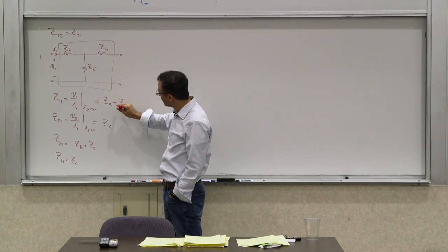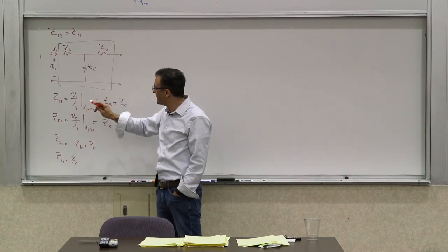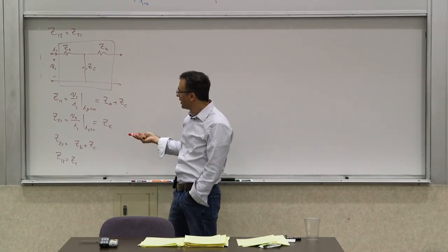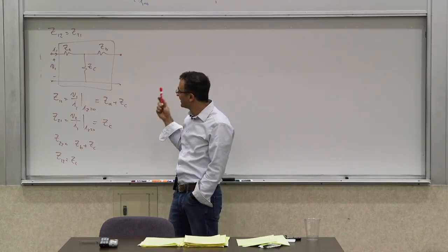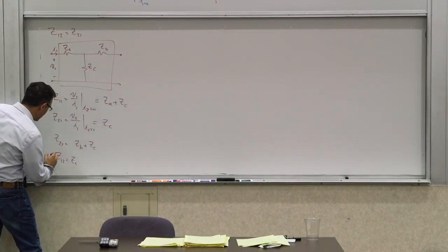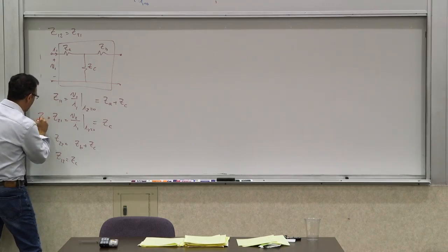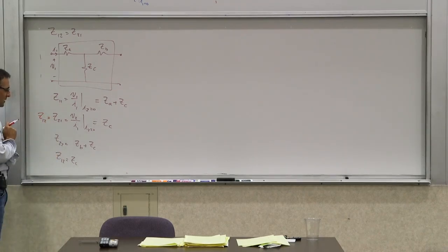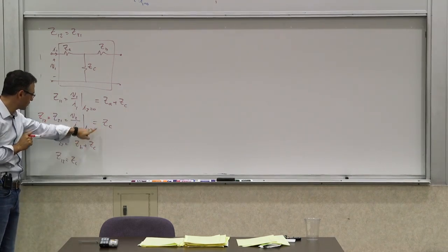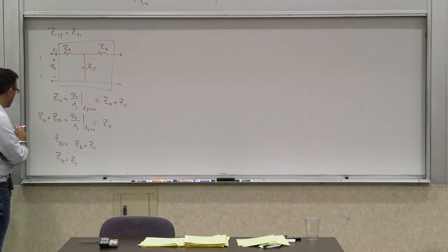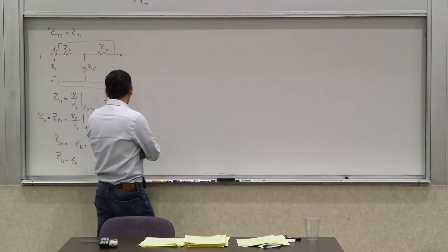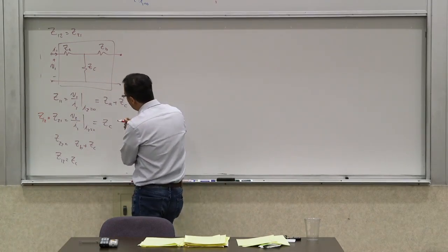Let us take another step and solve for ZA, ZB, and ZC in terms of the Z parameters. In general, you don't have enough information. But if we take this assumption, then you can say this is the same thing as Z12. And in this case, this is indeed reciprocal, because Z12 and Z21 are the same. So if that's the case, let's solve for ZA, ZB, and ZC.